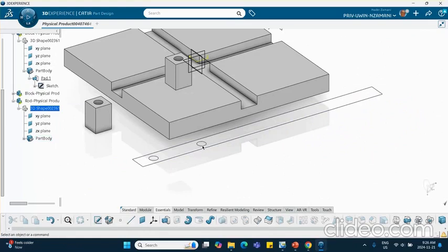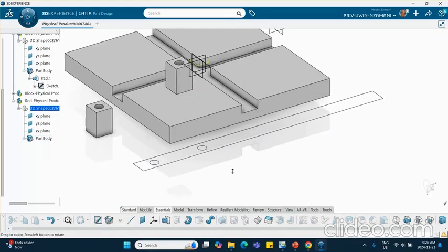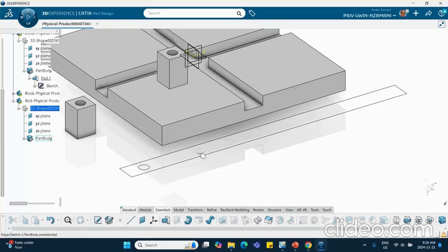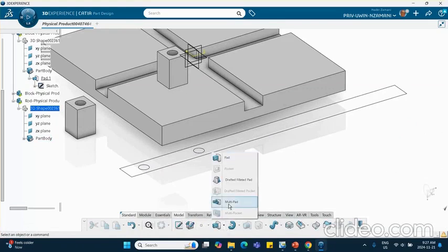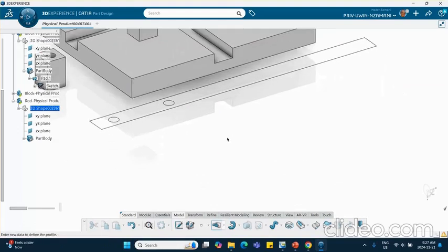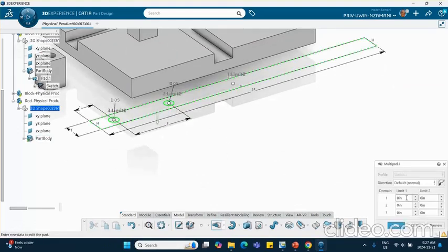Now I want this to turn into a pin and this thing to be thickened, okay? Now, if you do a pad of this, there will be holes here, and you can solve the problem, but I'd rather make these pins. I could have drawn this rod here, and then on it drawn a circle and padded it. But the alternative is to use the multi-pad. Okay, multi-pad. You select that sketch. It tells you that there are 3 curves here. So if you want a hole, make the height 0.